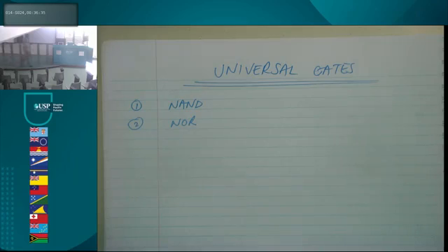Okay? All right, now, you have these two gates, the NAND gate and the NOR gate, right? These two gates are gates with which you can build any other gate. So if the technician or the shop says, sorry, we're out of stock of AND gates, you can always build an AND gate using a NAND gate. Or if you have only NOR gates, you can build it using a NOR gate.